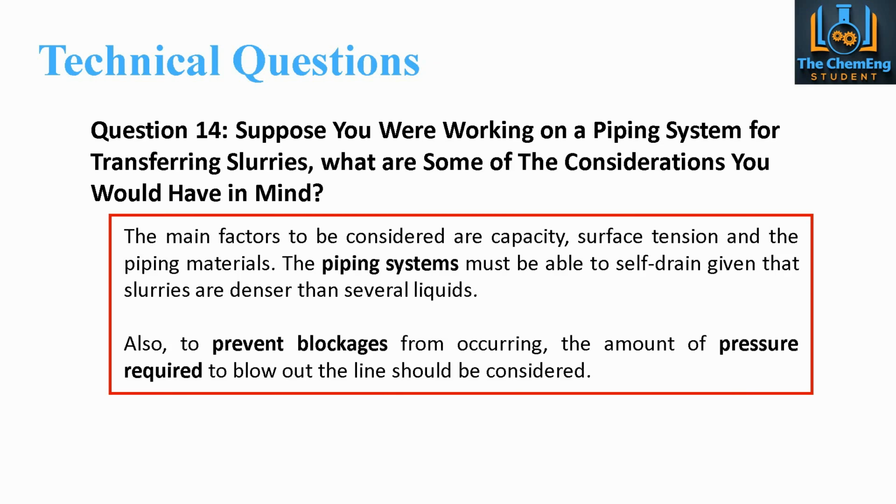Now we'd also need to have in mind that the piping system must be able to self-drain, given that the slurries are denser than different liquids.